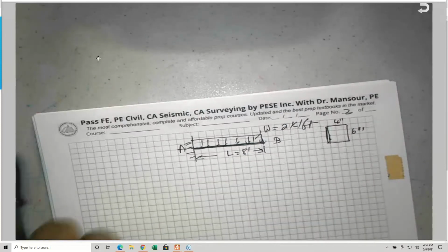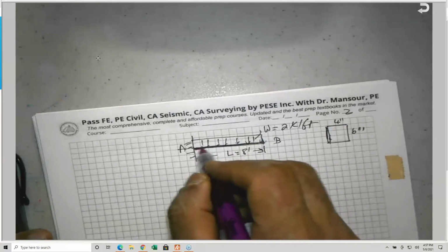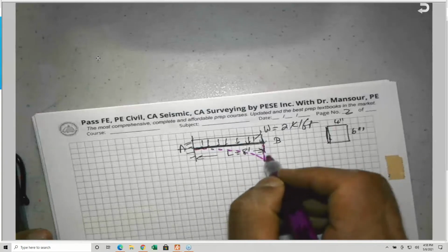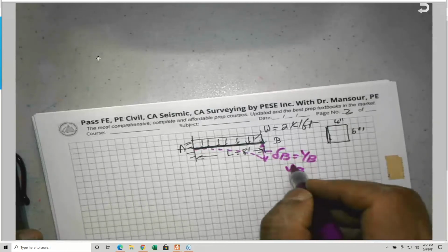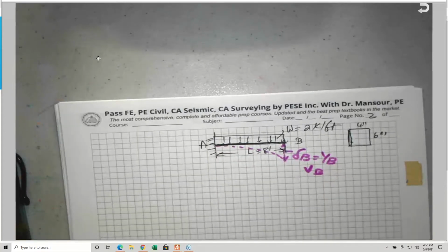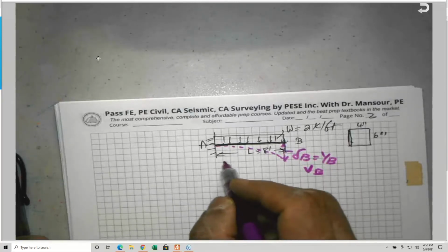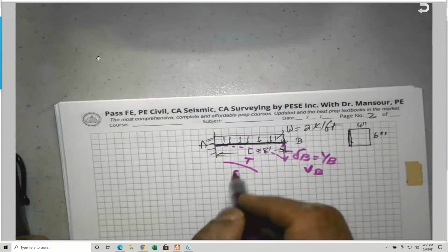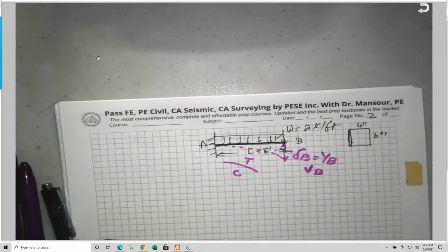We are expecting this beam will deflect as shown. It will go down, and we are going to see the equations for deflections, which they are providing. So this is the maximum deflection, delta B. They call it y sub B, I believe, in the book here, or sometimes v sub B also. We'll see deflection. But this is a negative bending moment. Why negative? Because the beam is doing this, so this is tension and this is compression. So this is the unhappy face. This is why, when you draw the shear and moment diagrams, you will find that we have the following.